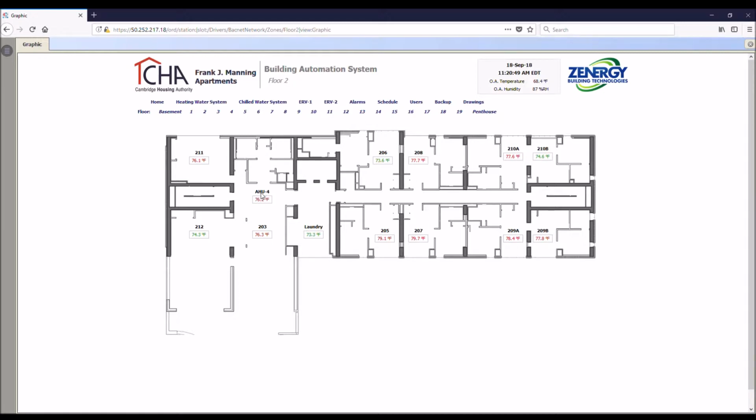KMC's plug-in thermostat basically just communicates to a remote controller at the unit, whereas for the other fan coil units and everything, the thermostat itself is the controller that everything is wired to.